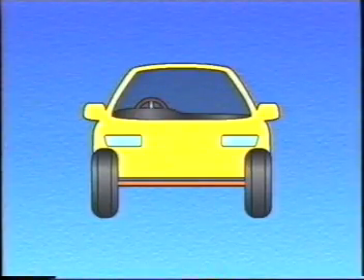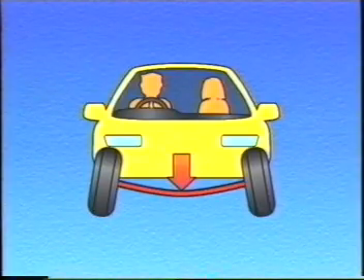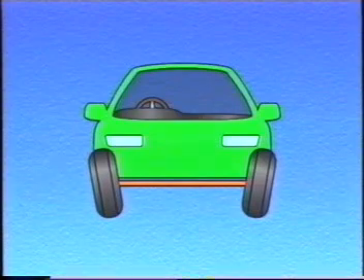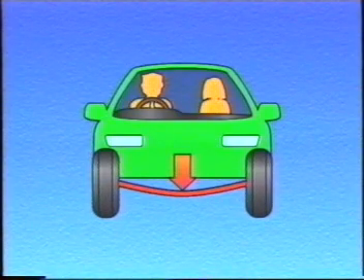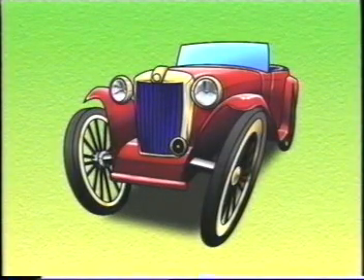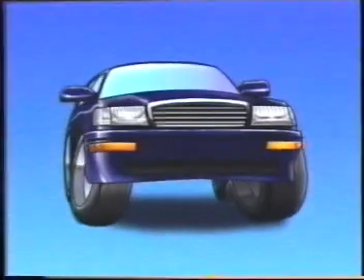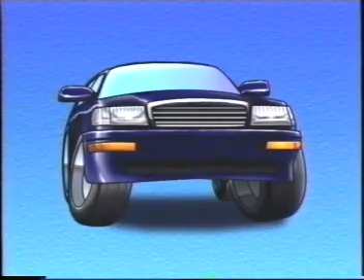In some suspension systems, the load on the axles makes the tops of the wheels tend to tilt inward. So giving the wheels positive camber helps to prevent this. Usually, for these reasons, positive camber was commonly employed on most vehicles. However, recently, improvements in such things as suspension performance make the need for positive camber less, and the employment of wide tires makes 0 or negative camber standard.